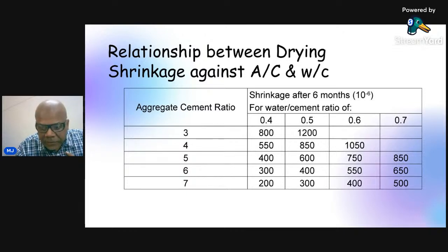Yogesh, lovely answer. Fantastic. So Ajay, thanks a lot. Thanks a lot, Mr. Patel, for answering. So 0.25 is the chemical demand for your cement. This means for a 50 kg bag, 50 multiplied by 0.25 is 12.5 liters. That's all the water it needs.